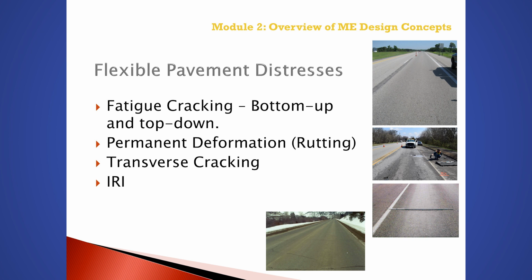The International Roughness Index, or IRI, is also predicted for asphalt pavements, but is included at the end of this section because it is considered a performance indicator that is applicable to all types of pavements. More importantly, similar to rigid pavements, no mechanistic response is used to predict IRI over time for asphalt surface pavements.